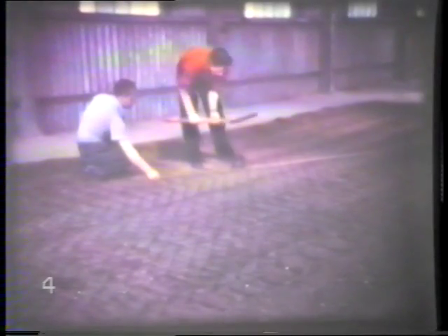The state of compaction of the soil is measured in terms of the dry density. That is, the weight of the dry material per unit volume of compacted soil. In order to ensure that an accurate and representative result is obtained, 10 determinations of dry density are made over the compacted area. Personal bias in selecting the points where these measurements are to be made is eliminated by employing a standard pattern.